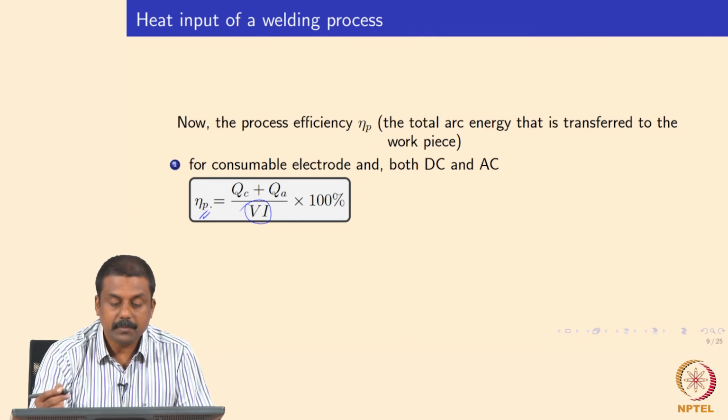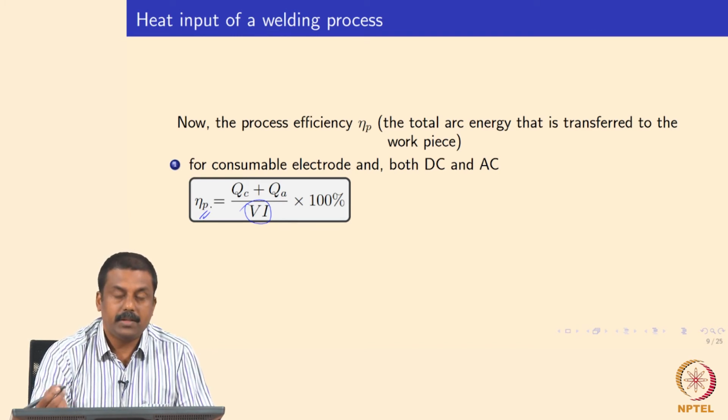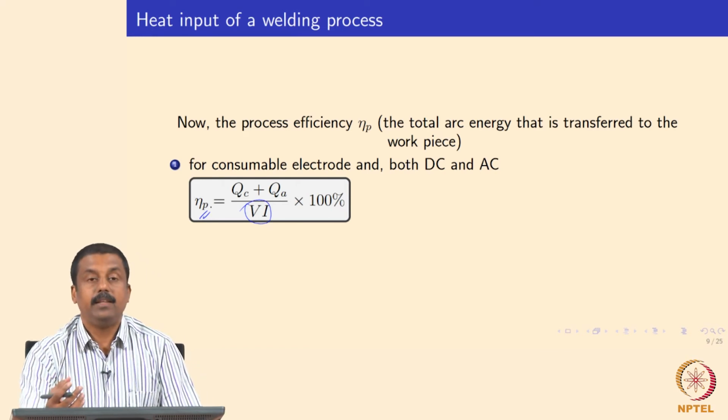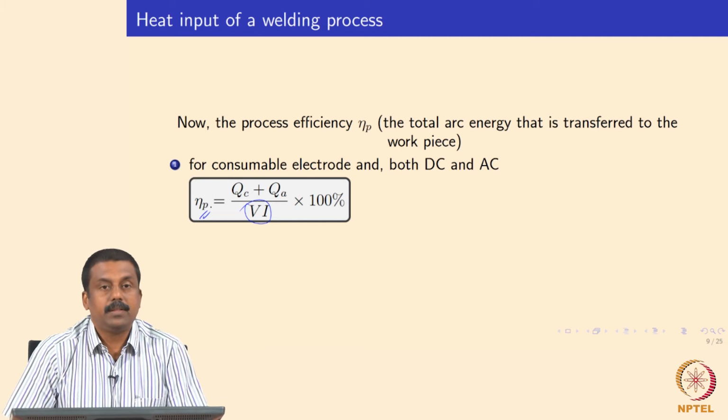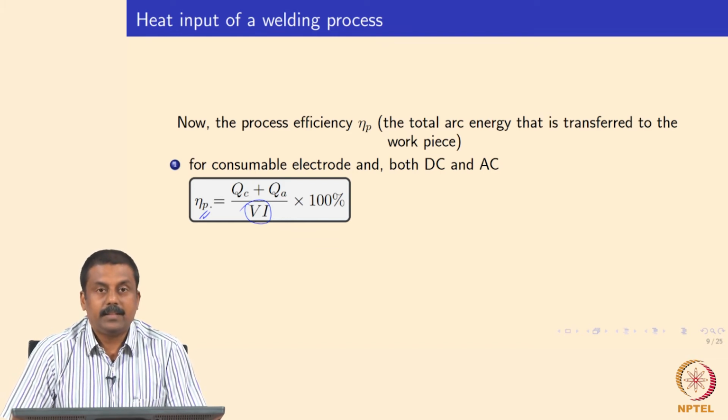In the conventional GMAW process, the energy efficiency is not that significant, but it is much higher than in the laser welding process, because in laser welding we already looked at how the absorption of laser by the workpiece is extremely small. Whereas in this case, the heat transfer from the arc is entirely determined by the atmosphere as well as the polarity.